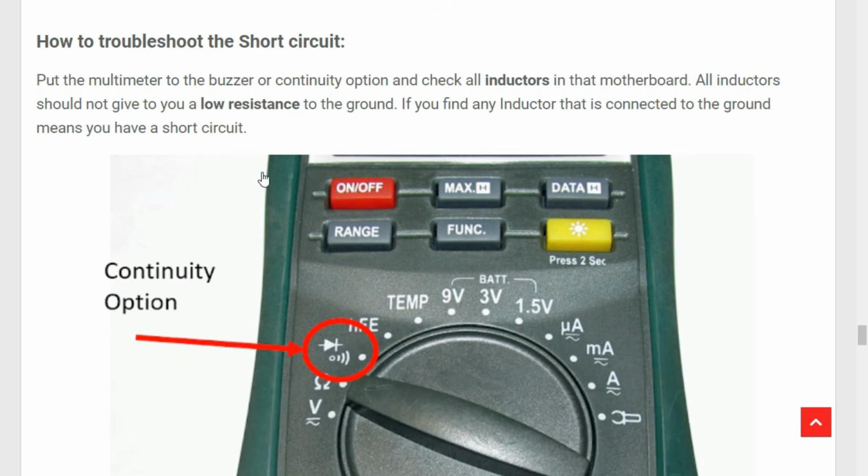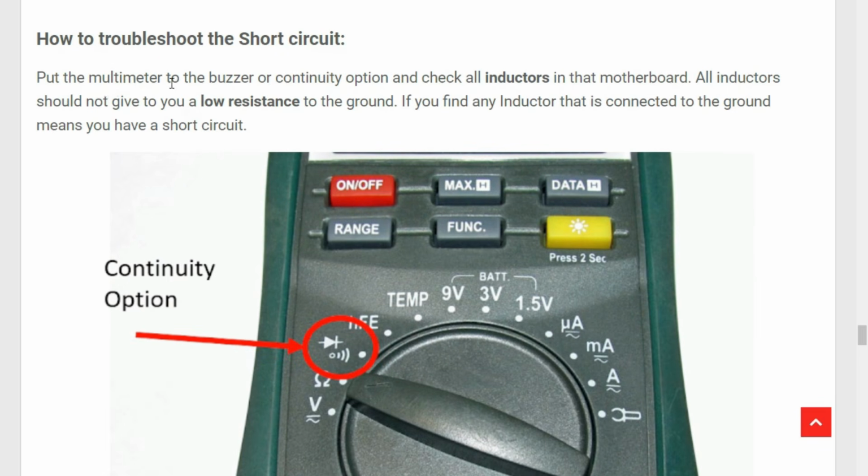How to troubleshoot the short circuit? Put the multimeter to the buzzer or continuity option, as you can see here.